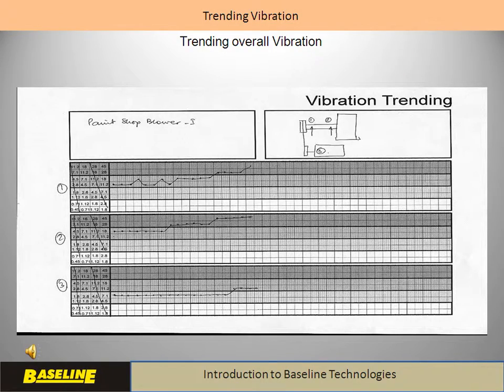A very simple form of monitoring vibration levels in machinery is to maintain a trend chart of vibration. In this chart, overall vibration velocity or bearing-related vibration levels are plotted over time, and the trend can help draw valuable conclusions regarding preventive maintenance.